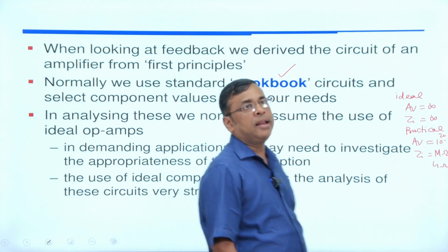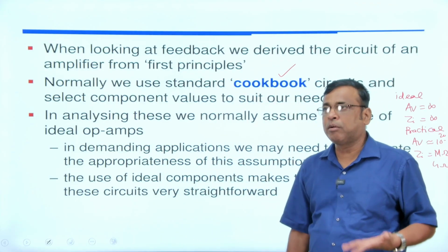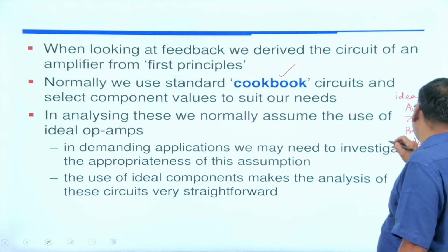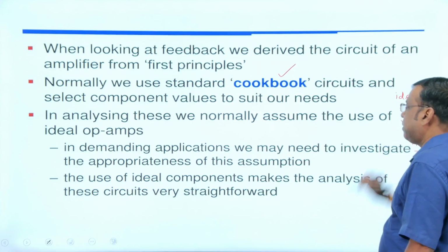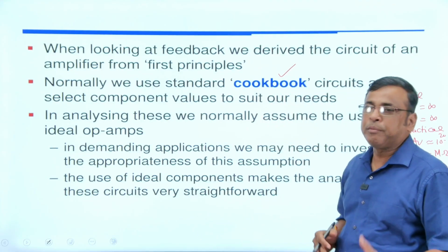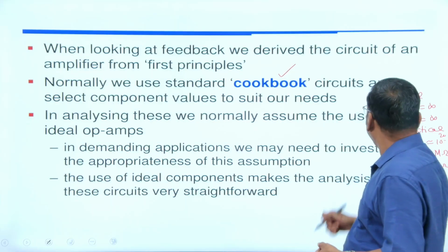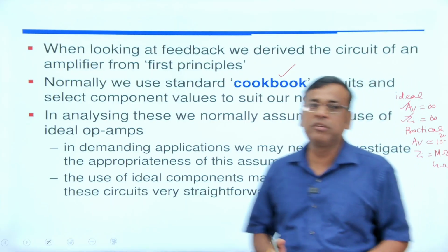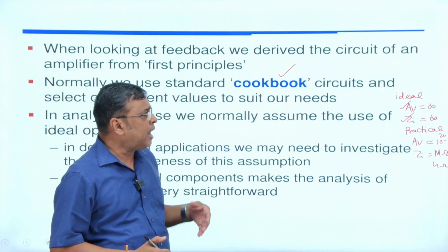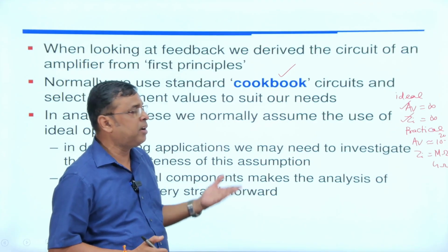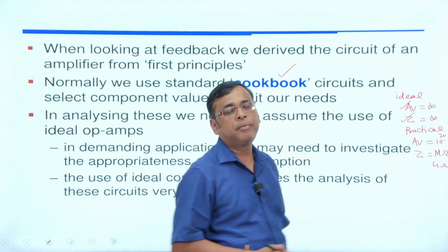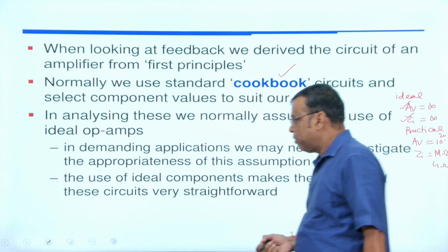But for analyzing electronic circuits, normally we analyze with an ideal operational amplifier, to make the calculation easy: the gain is infinite and input impedance is infinite. Suppose you are analyzing a particular electronic circuit; we consider the ideal operational amplifier, then find the output voltage, the input voltage, the gain, the input impedance and the output impedance. In the ideal case, your calculation will be much simpler.